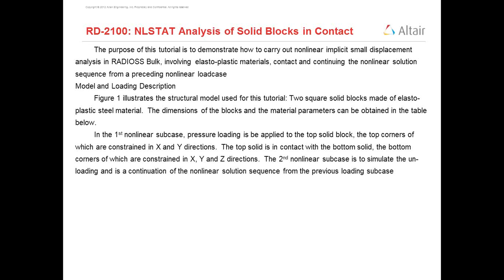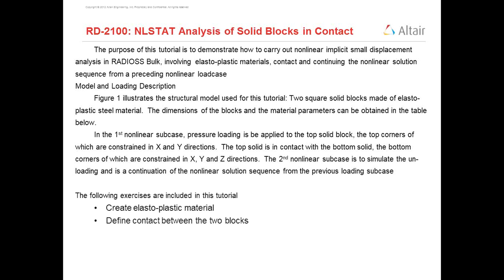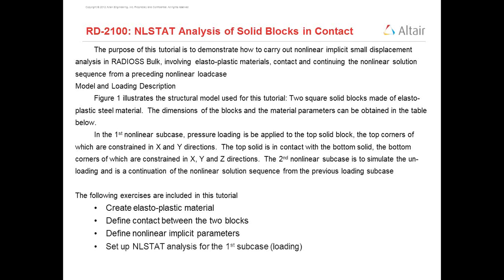The second nonlinear subcase is to simulate the unloading and is a continuation of nonlinear solution sequence from the previous loading subcase. The following exercise includes create elastoplastic material, define contact between two blocks, define nonlinear implicit parameters, set up NLSTAT analysis for first subcase loading, then set up NLSTAT analysis for second unloading subcase, and submitting the job in Radioss for the analysis and viewing the result.